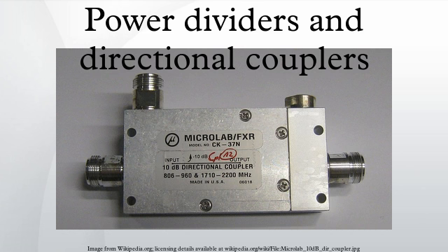Power dividers and directional couplers are in all essentials the same class of device. Directional coupler tends to be used for 4-port devices that are only loosely coupled, that is, only a small fraction of the input power appears at the coupled port. Power divider is used for devices with tight coupling and is usually considered a 3-port device. Parameters. Common properties desired for all directional couplers are wide operational bandwidth, high directivity, and a good impedance match at all ports when the other ports are terminated in matched loads. Some of these, and other, general characteristics are discussed below.